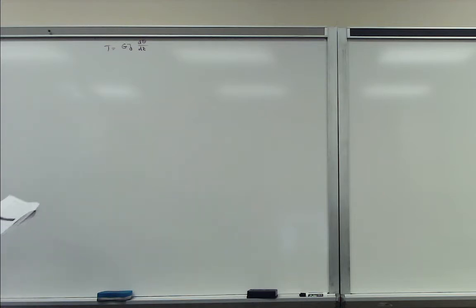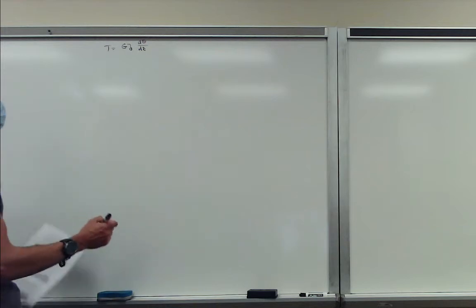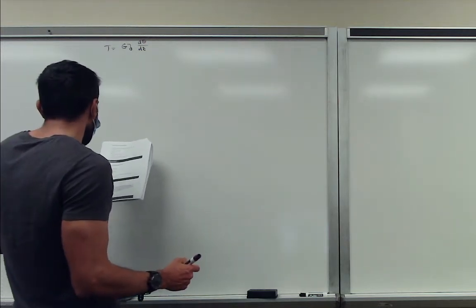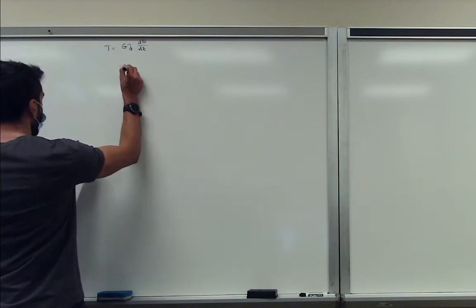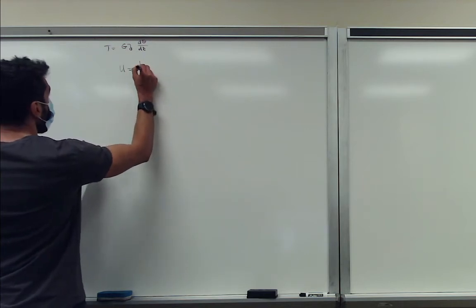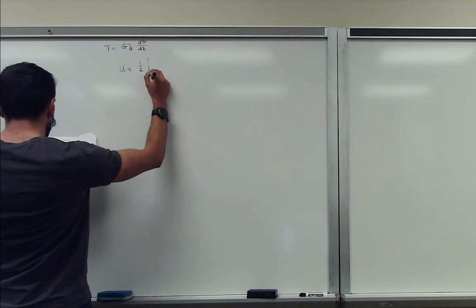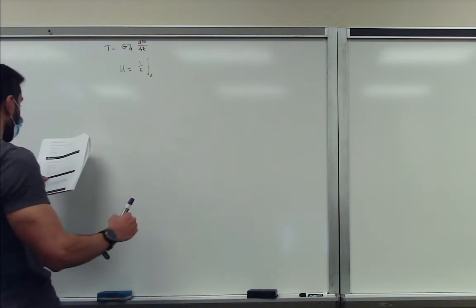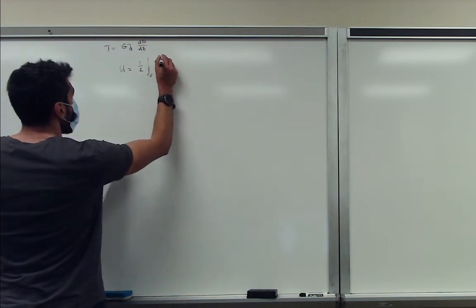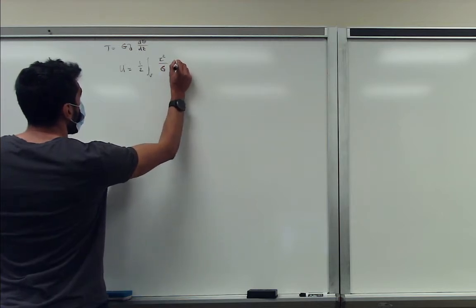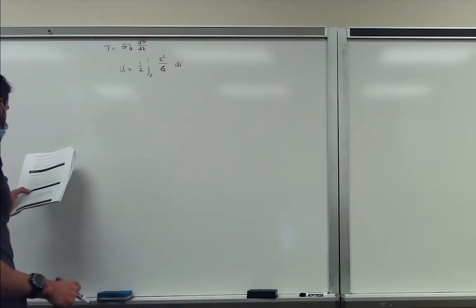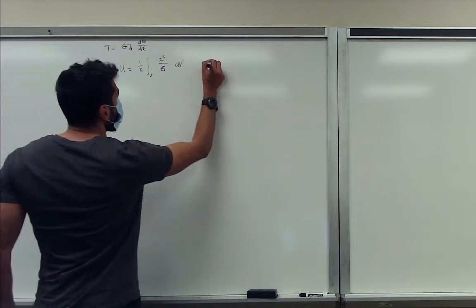And the method that I'm going to use is basically an energy method. So we define the total work done, or total energy in our system, and we define that as equal to 1 over 2, so half times the integral over the volume of the shear stress squared over the shear modulus integrated with respect to the volume. So this will be our total energy.